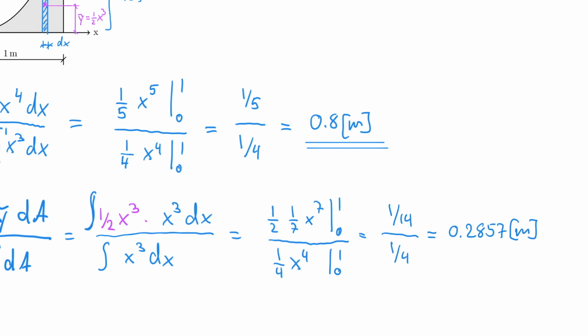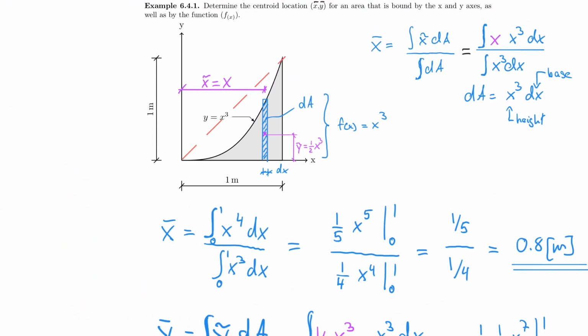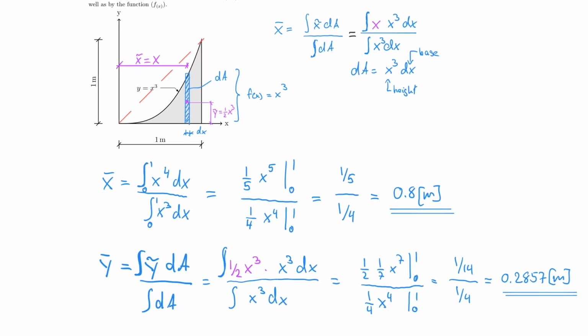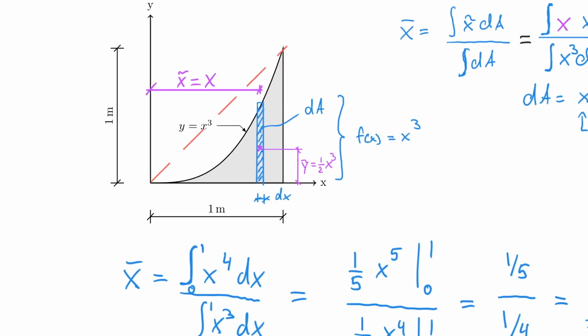And so now I need to double check that result as well in my sketch. In fact, the very last step that I have to do is really look at my sketch, but it was less than 0.3. And that makes sense as well, right? Because the heavy side of this, what used to be a triangle, is here on the bottom. And so if I carve this part out, it slides more down. And so for a triangle, it would be 1/3, which would be 0.33. But the carving makes it drop further down, and therefore I'm done.